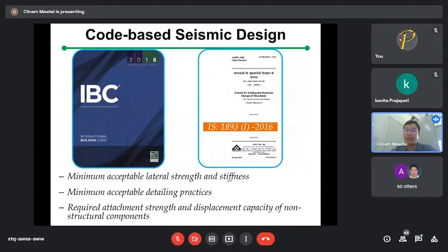Even for IS 456, how did you design it? You designed the shear force and the moment. But how did you check the serviceability? You check the deflection criteria, L by 20, L by 25 for simply supported condition. For the continuous support condition, you are also checking the deflection criteria, right? So whatever our design, performance-based design is an updated version of your limit state design. Don't think performance-based design is totally different from the existing design.